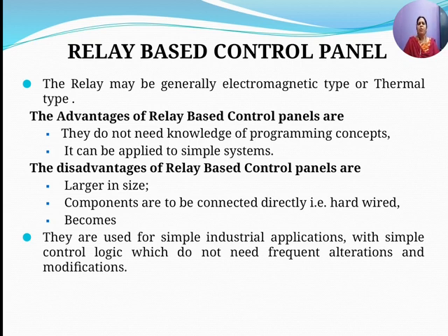Why is knowledge of programming not needed? When the sensor is placed on the conveyor belt, as in the example I have told, the sensor will be wired to the coil of the relay and the power supply. The NO contact of the relay will be wired to the electrical motor.